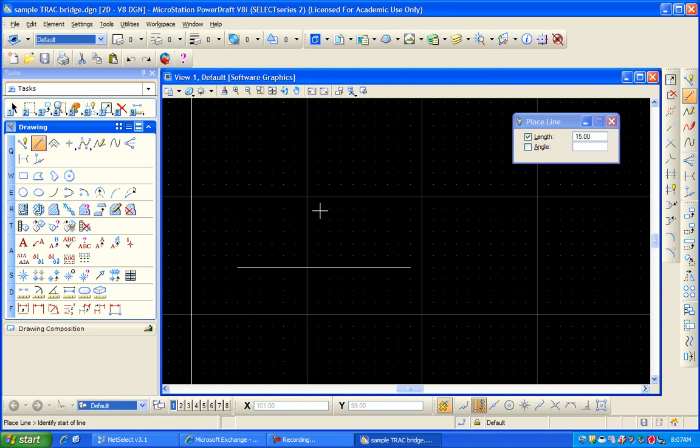So in order to do that, I'm going to go ahead and copy this line rather than try to draw one out and fit it on the grid. And to do that, I go to the manipulate tools that I placed over here where copy's at, and if you go down to where the two squiggly lines are at, that's your move parallel or copy parallel. So I'm going to go ahead and select that feature, and it's telling me select the element I want to move.